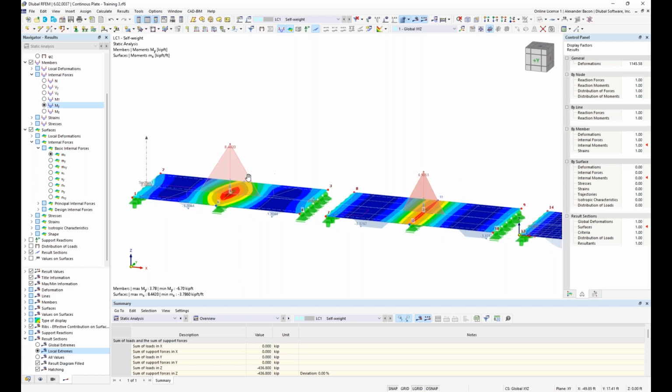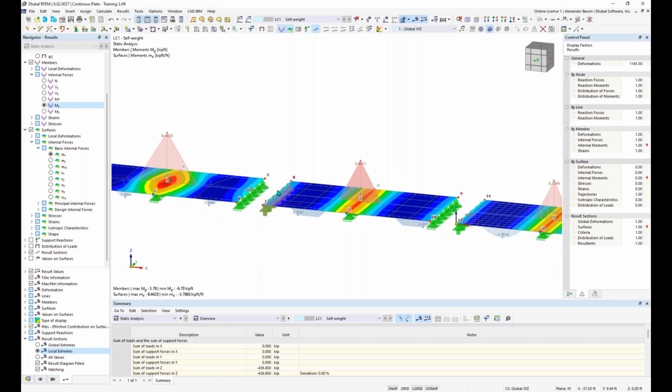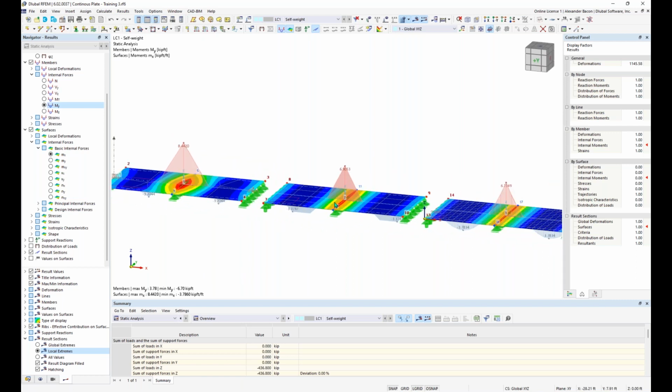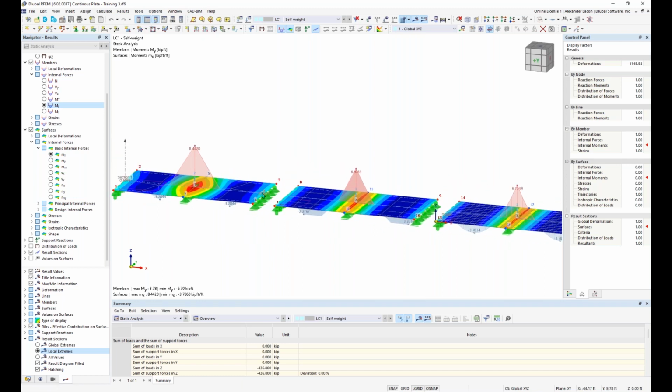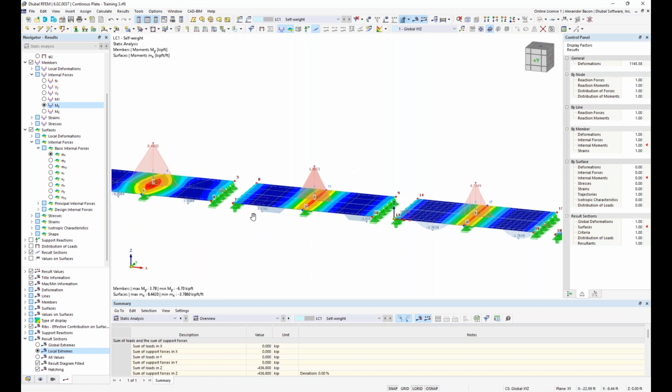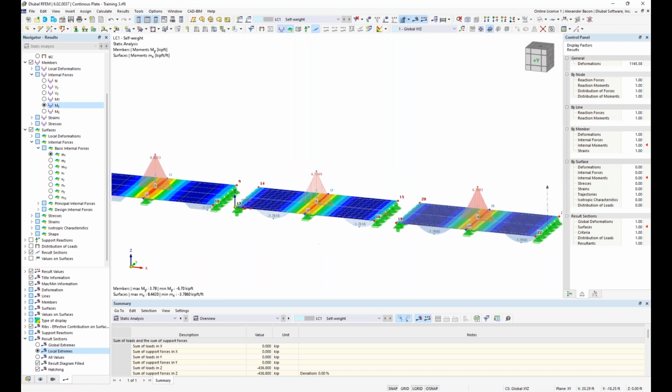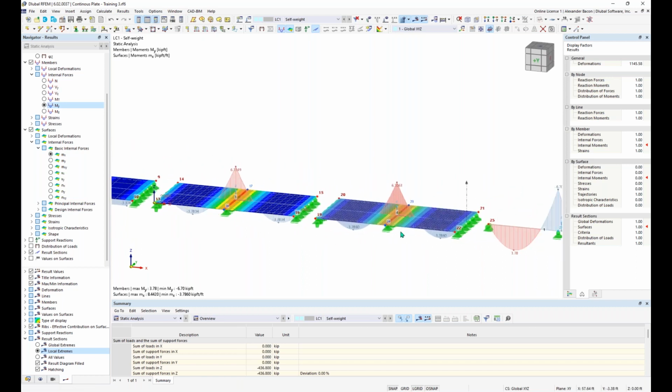So the finer the mesh gets, the more points of, well, results are only being calculated at each FE mesh point or node on the first surface here. And so the finer the mesh gets, the more points of data we have, and then the more accurate results. So keep in mind though, if your mesh is too fine, your calculation time will increase. And so you want your mesh as fine as necessary, but as coarse as possible.